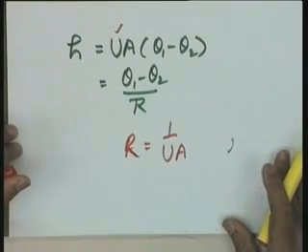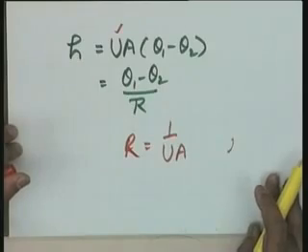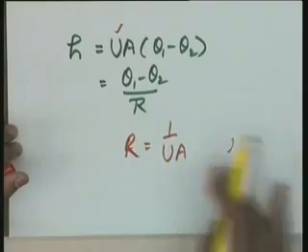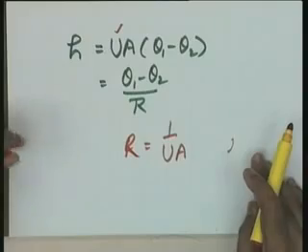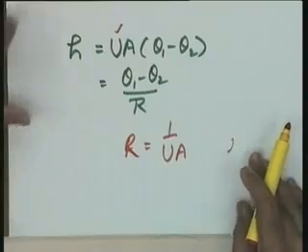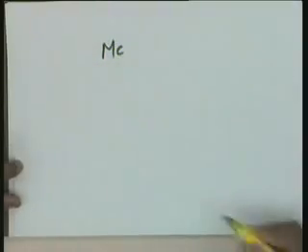You will see that the parameter of interest to me will be the resistance parameter as far as the dynamical behavior of the thermal system is concerned. The capacitive parameter comes from the heat storage. Look at the heat storage, the same wall example which I had taken. The heat storage will be given by MC.